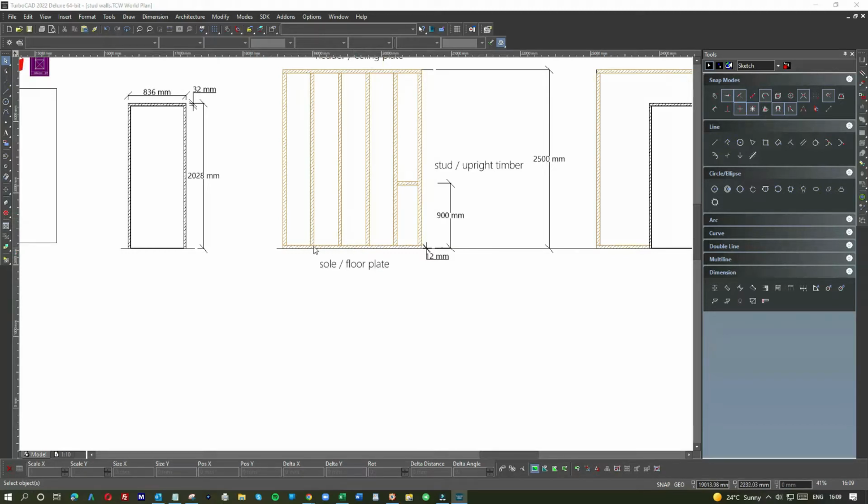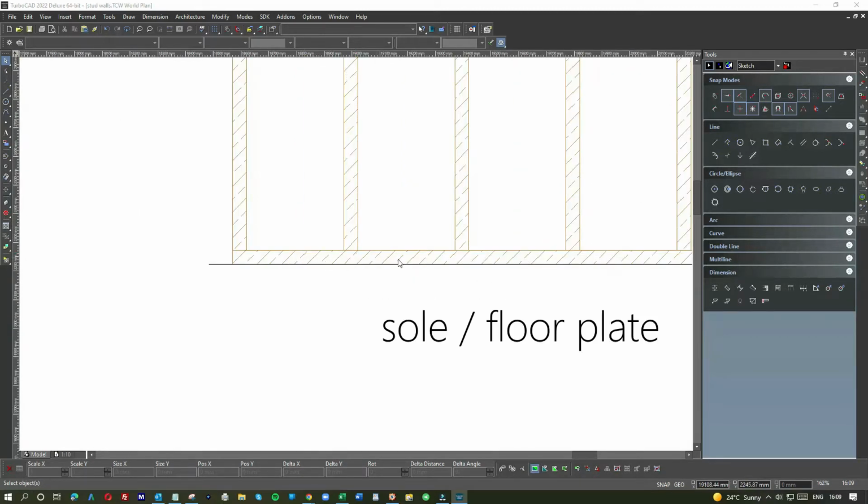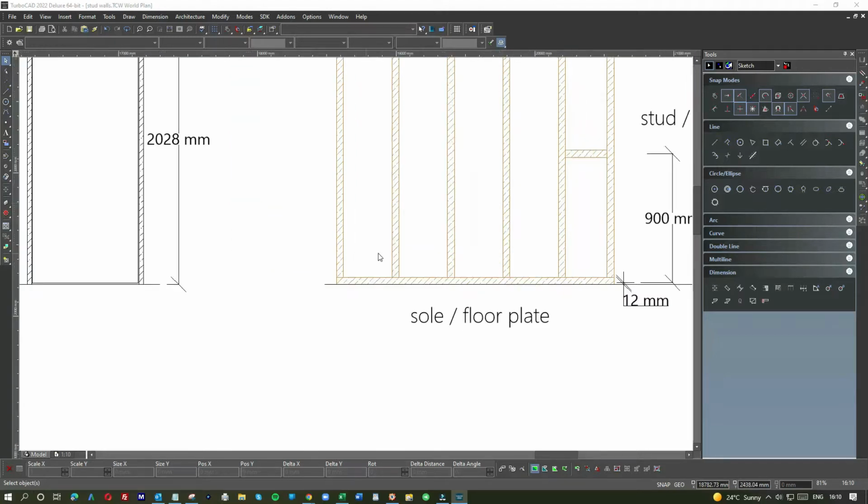So, for example, on the base here now you've got a 4x2. This is a 4x2 stud wall, or 100 by 50 if we're on millimeters. Traditionally, even though it's in millimeters and the timber is sized in millimeters, in the UK building trade, the reference to it is 4x2 stud.